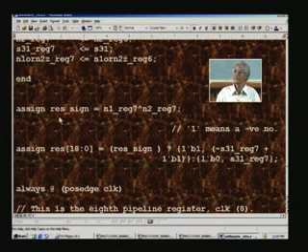Exclusive ORing is simple in logic because you know the simple multiplication rules. If you multiply plus into plus, you get plus, minus into minus is plus once again, so long as both these sign bits are the same, whether plus or minus, the result will be plus. If one is plus and the other is minus, you get a minus. Minus is represented as 1 in binary, and 0 is positive. So when you exclusive OR 0 and 0, which stands for plus into plus, out comes 0.